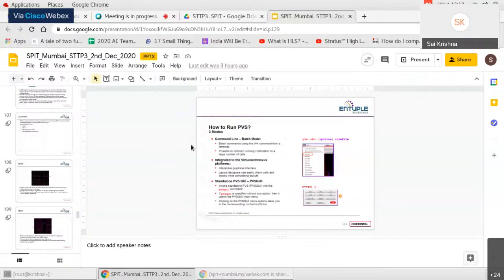So in timing sign off, we perform static timing analysis, and if there are any violations found there, in the presence of parasitics, we have certain techniques like adding or removing buffers, upsizing or downsizing cells, adding or removing redundant buffers for setup based on what you're treating, setup or hold. And then you'll check for IR drop, static and dynamic, and electromigration in your power analysis and sort it out.